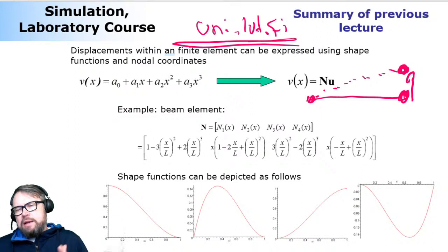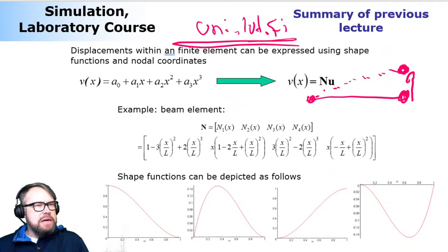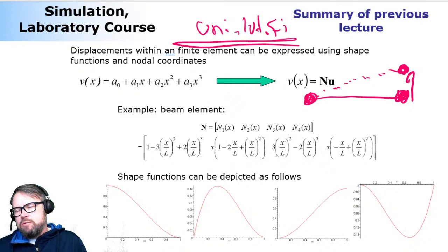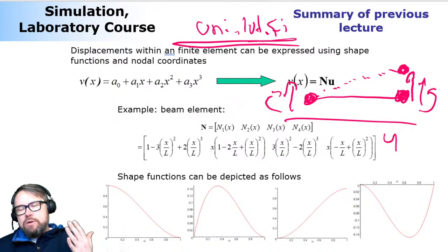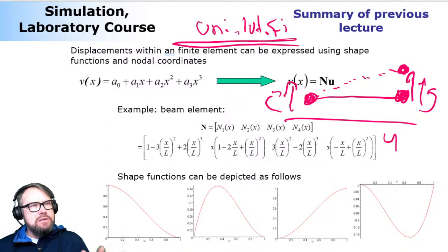All right. Now, how can you select the proper polynomial? Well, of course, it depends on what kind of element you would like to predict. Let's go back to this beam-like element that consists of two nodes, and each node has 2 degrees of freedom, which are displacement in the transverse direction and rotation. Then this element will have a total of 4 degrees of freedom. So you need to predict this by using 4 unknown polynomial coefficients. And how you can select those will come from the famous Pascal triangle, which tells you how you can possibly select these polynomials.